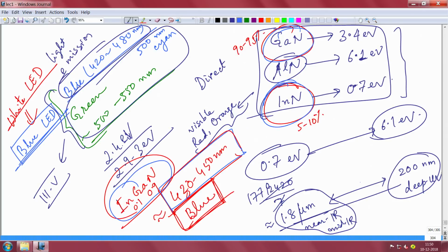Before I go to the unit crystal structure and the polarization, I'll still revise a little bit here, that gallium nitride, aluminum nitride and indium nitride can enable a large range of band gap here. And this is why it has been very promising. It has enabled the blue and the green LEDs, and laser diodes are something that only gallium nitride technology has enabled efficiently. Before the advent of gallium nitride in the 1990s, people couldn't get blue emission, and it was very inefficient,